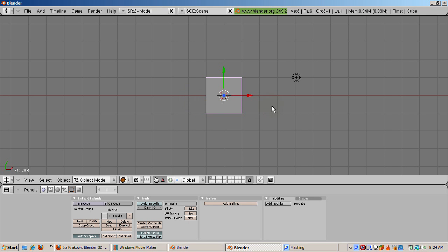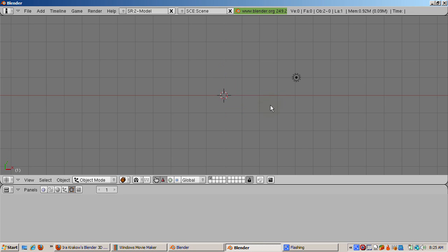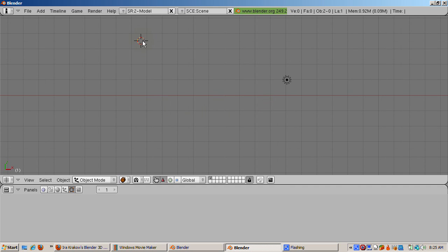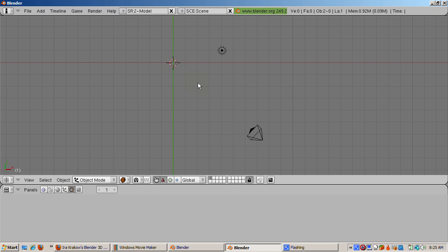So fire up Blender, delete the default cube: right-click, X to delete, and Enter to confirm. If you click inside the 3D window, the 3D cursor goes to the place where you click. That's the place where the next object will be created. We want the text to be placed at the origin: X equals 0, Y equals 0, and Z equals 0. To do that, there's a simple shortcut to place the 3D cursor there. Press Shift-C. To create a new text object, you do space, add text.